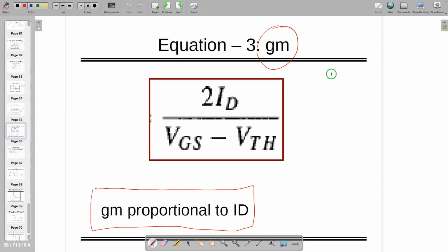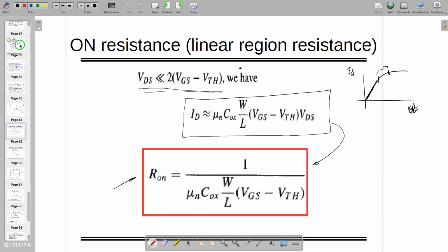Designing means op-amp design or amplifier design. I'm saying those techniques and other things are actually limited to analog designing. For the case of digital MOS LSI circuits, it's going to be different, right? Then you don't follow all this, because first of all we are following the square law equation. In that you are not going to follow the square law. You are going to follow the triode region equation, right? So you have to follow the Ron rather than going into gm. So Ron is very, very clear, right? It has only one equation. There is no variety, right? So it's a simpler one.